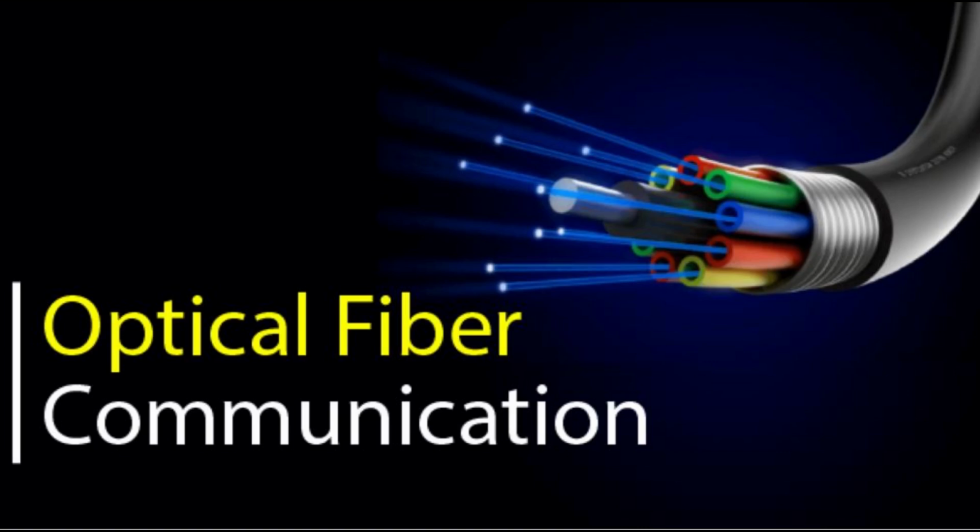To renew, or boost, the signal throughout its journey, fiber optics transmission sometimes requires repeaters at distant intervals. These repeaters regenerate the optical signal by converting it to an electrical signal, processing that electrical signal and retransmitting the optical signal. Fiber optic cables are now able to support up to 10 Gbps signals. Typically, as the bandwidth capacity of a fiber optic cable increases, the more expensive it becomes. Multi-mode fiber and single-mode fiber are the two primary types of fiber optic cable.